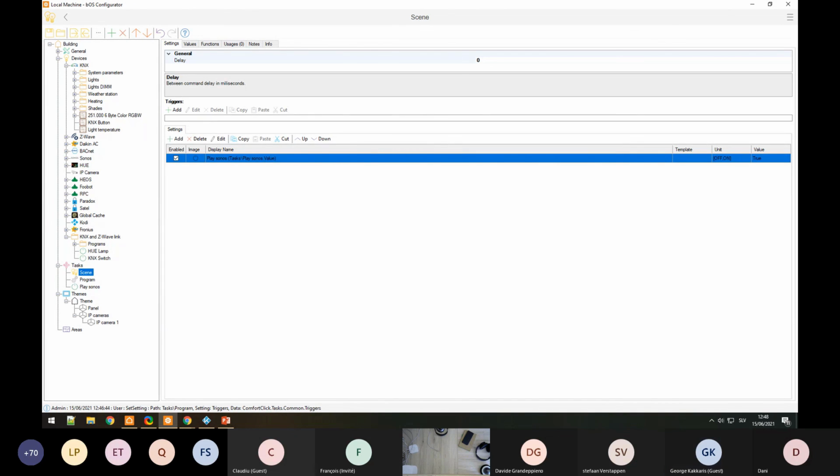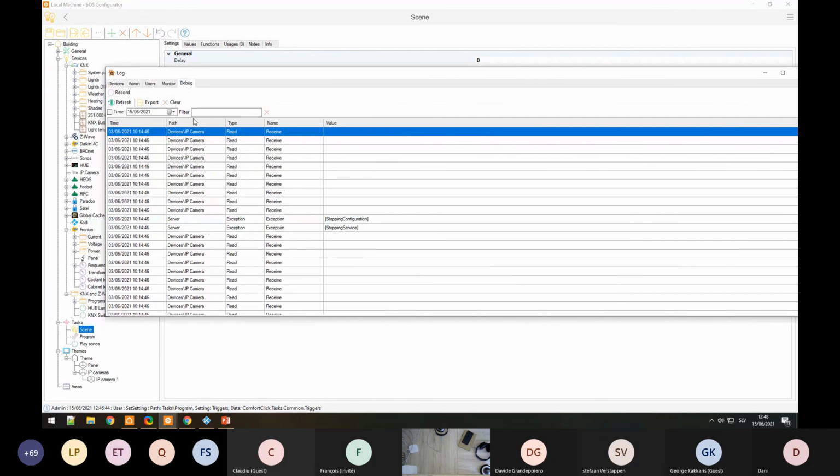Well, which relay panel is this? In order to control the Modbus relay panel, you should decode the hex codes, or you can try and error by enabling this debug log.